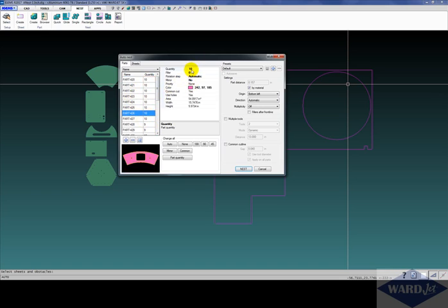And then over on the right, you've got a dialog box where you can change the various values for the different parts. So one thing you can do is specify filler parts. The quantity would be the quantity of parts that you definitely want to get, and then the filler parts can use up to that many parts to either fill up an entire sheet or just the portion of the sheet that's being used by the parts that you really want. So on these 4 parts here, I'm just going to select those, and I'm going to specify 50 fill parts for each of those. So we want 100 of this part plus up to an additional 50 fill parts.